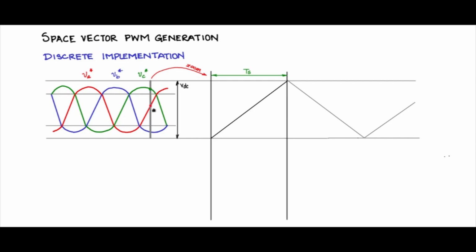There is an intersection point here for the VA waveform, and there is an intersection point here for the VB waveform. So let us extend that so that it cuts this voltage to time conversion ramp like that. So this height is VA height, I will say. This height will be VB height, and this height up to this would be VC.